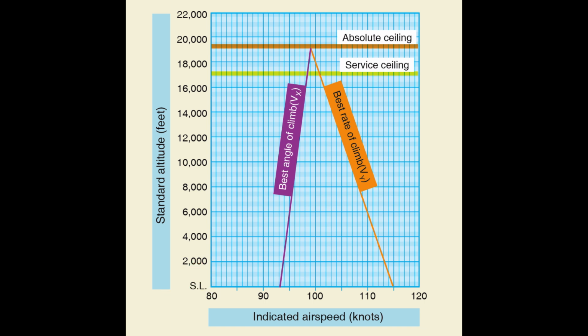Establishing a climb. A straight climb is entered by gently increasing back pressure on the elevator flight control to the pitch attitude referencing the airplane's nose to the natural horizon while simultaneously increasing engine power to the climb power setting. The wingtip should be referenced in maintaining the climb attitude while cross-checking the flight instruments to verify performance.